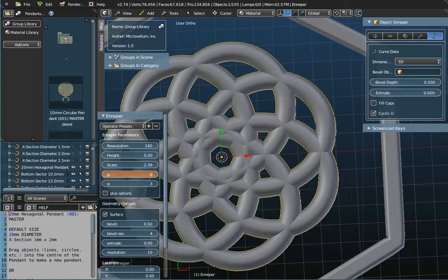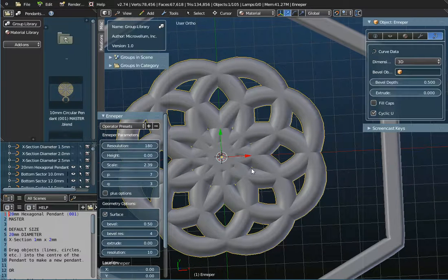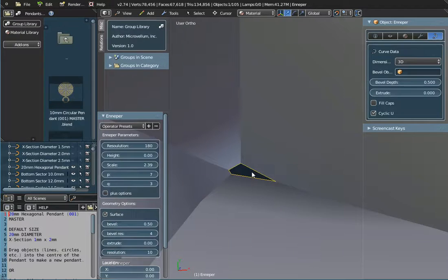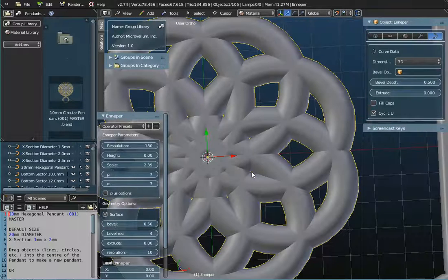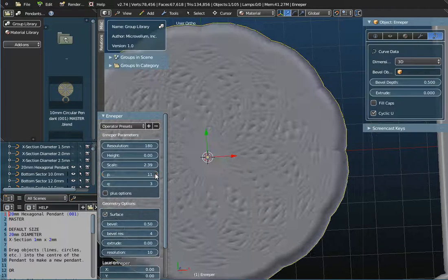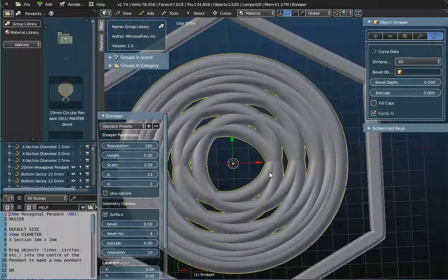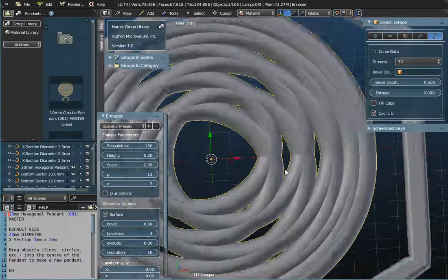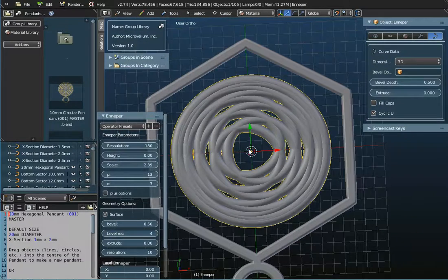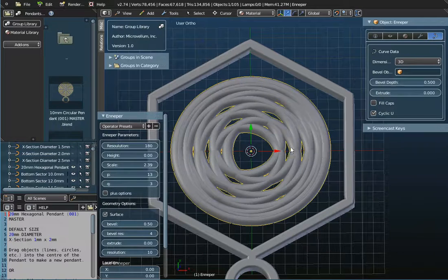So if we keep increasing P, these shapes, we're not going to see that. We're certainly not going to get the hole that's there, because that's just far too tiny to be seen when 3D printed. So as we start going up higher and higher, clearly you can see that the pattern isn't going to work very well. Those gaps would probably be okay, just about though, because that's 0.4, so you probably just see a hole there. You certainly see the hole in the middle. But that's pretty much all you get.